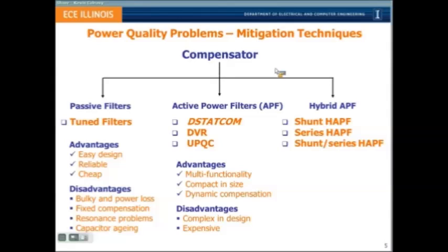What this does is we insert a series voltage along with the supply voltage. Let's say whenever the supply voltage suffers a dip, this inverter pumps in a series voltage along with the source. They tend to add up together to create the nominal desired load voltage. So that's the action of DVR.